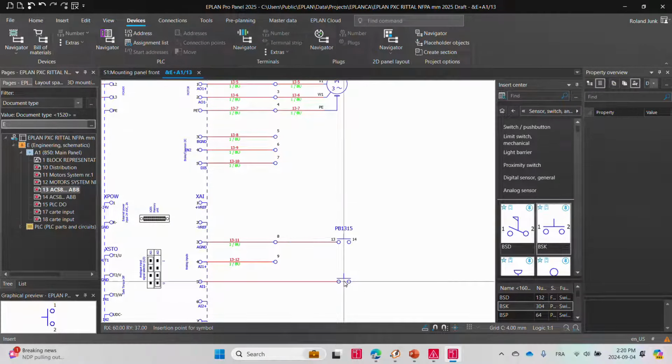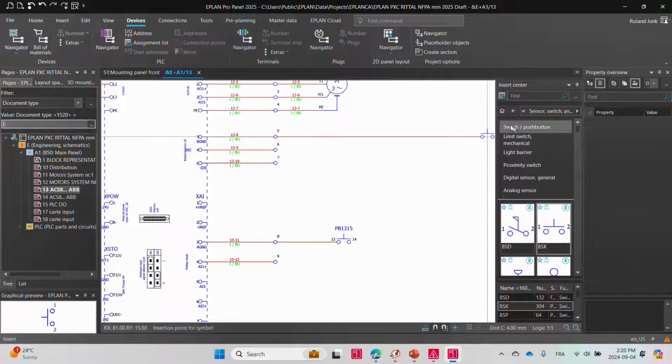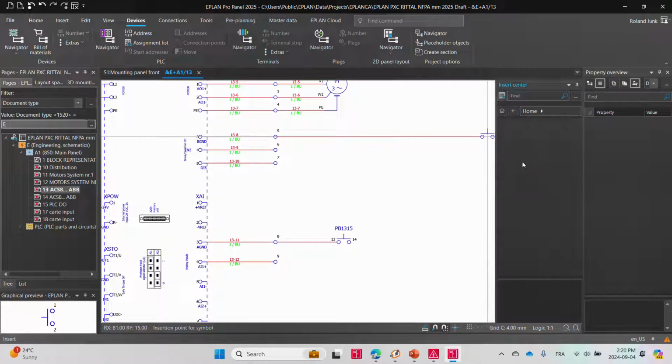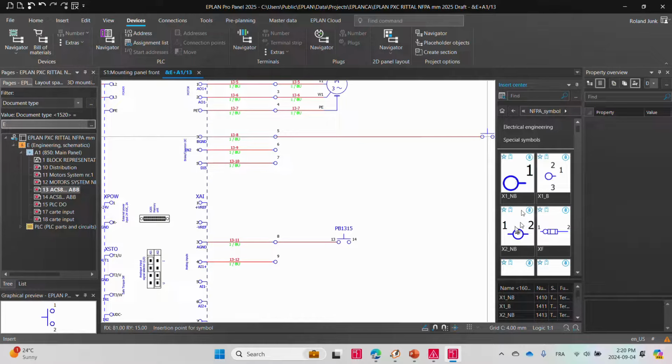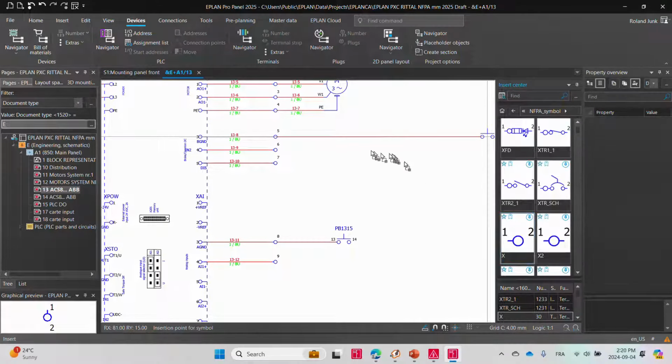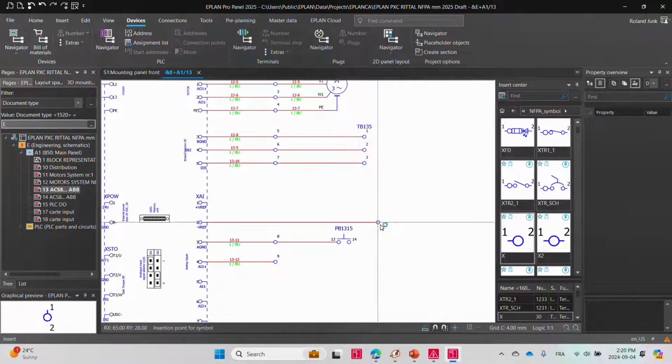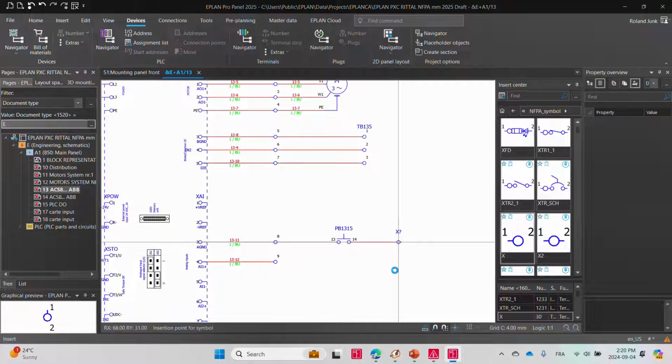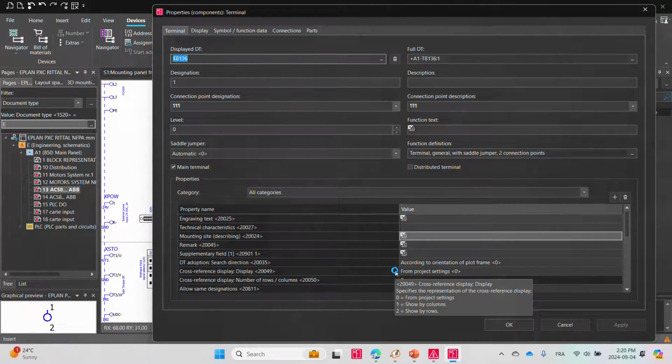There's another trick that is quite interesting too. If you wish to position multiple elements at the same time, it's a very nice trick. Let's say some terminals. I have a row of terminals that are part of a junction box. So maybe here, 1, 2, 3. Just drag and drop it down, boom, boom, boom, and you will have 3 new wires. Of course, I can put another wire here. I can put another wire there. Every time I put an element, it actually numbers automatically.